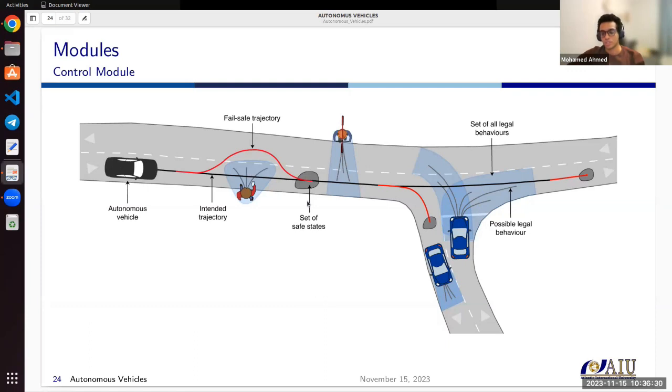It's worth mentioning that it looks so easy, like you can use maybe an A star planning algorithm or any sort of algorithm, but there is another challenge that can face you here. For example, the algorithm can give you a path that is near the edge, but your robot's dimensions need to be taken into consideration. If the path was going here, that means if you follow this path, then your car will be out of the road. That's something you need to keep in mind.